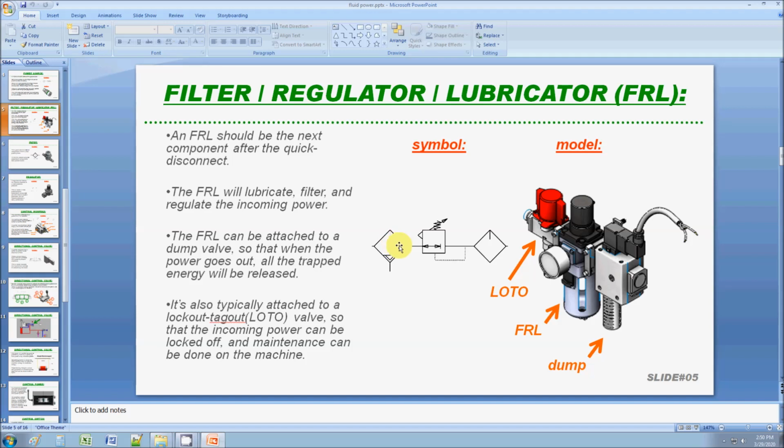So there are many different gadgets to make a machine locked out before it can be maintained. In this example here, you have this switch that gets rotated. It's got some sort of spring inside, but you rotate it, and this notch matches with a notch on the lower end, and you place a lock through them to make sure that the machine does not run.